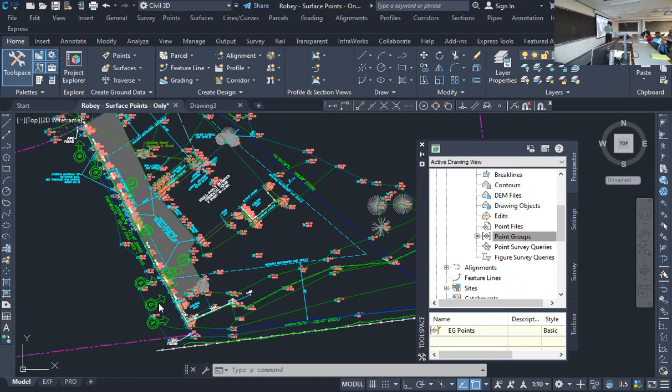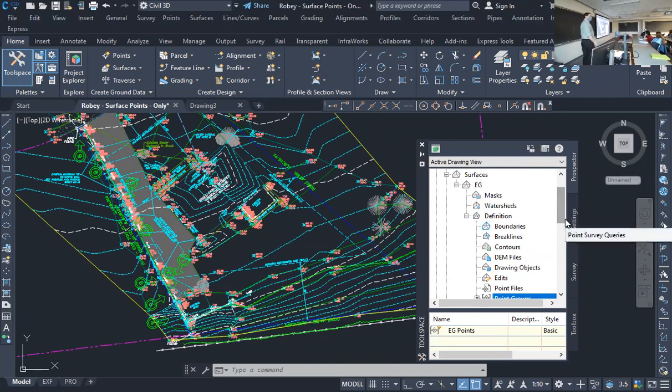Now it added the points in. Okay. So now, wow. See how long it took to generate that? But it created contour lines just from the points. Okay, let's take a look at this. The white lines represent every 5 foot interval, and then these are 1 foot in between. So let's say this is 100, 101, 102, 103, 104, 105. Everyone see that?